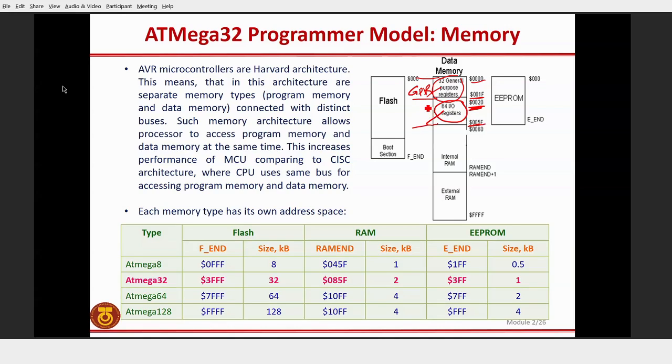There is actually a way to do it, but it will disturb the program, because each address in this I/O register is used as input or output. If you set your port A as an input, and suddenly you write something at that address, for example address 20 is for port A, DDR, to define it as input or output, then suddenly you write in your program that you want to use memory 20 to store something.